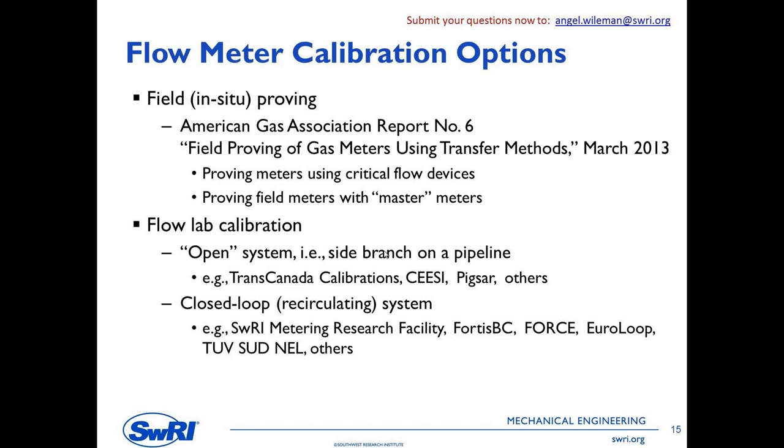If you're daring, you can do an in situ proving of meters. That means you can do it out in the field. There are people that are doing this now commercially as well. And for certain meter types, that's not uncommon to do. Small meters, low pressure applications, in situ proving is a pretty common thing.